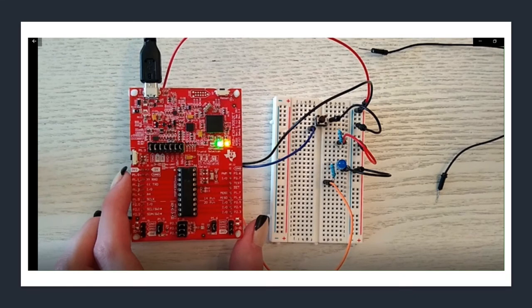I would recommend that when you're building your circuits, you can see I've used all black wires for anything relating to grounding, all red for power, and then other colors for various components. General good practice is to use those black and red wires for grounding and power respectively. And then just try to keep your board nice and neat so you don't have wires running everywhere.